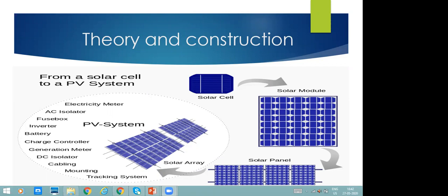Bypass diodes may be incorporated or used externally in case of partial module shading, to maximize the output of the module section. Some special solar photovoltaic modules include concentrators, in which light is focused by lenses or mirrors onto smaller cells. This enables the use of cells with a high cost per unit area in a cost effective way.